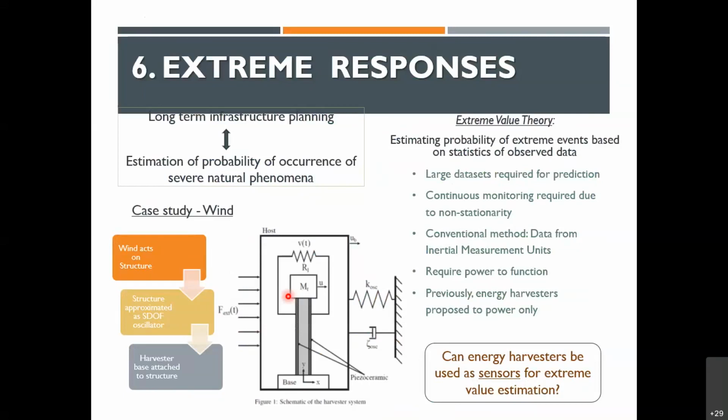And we tend to pick something at the tail of this histogram and say, well, at that probability in a standard normal space, this is the design value, and we are making our structure safe for this. Then, based on a certain model, let's say a Gumbel distribution or something, it corresponds to a 100-year return period. We call it a 100-year storm.